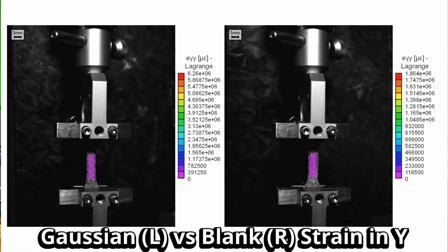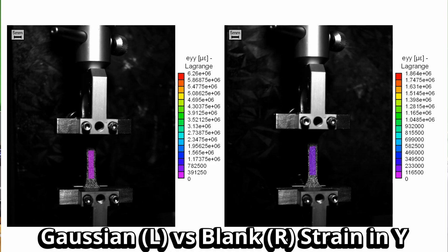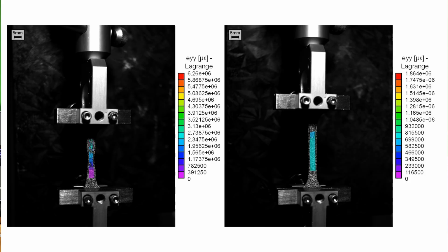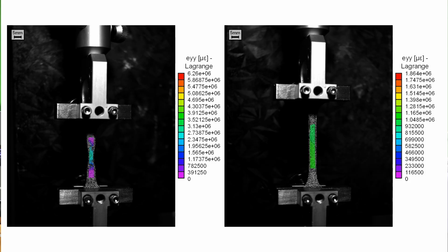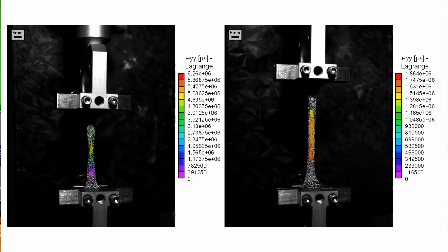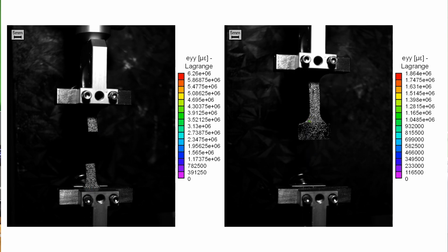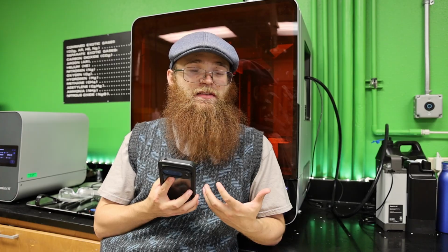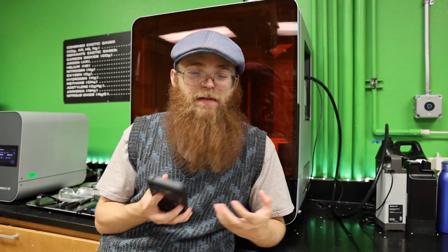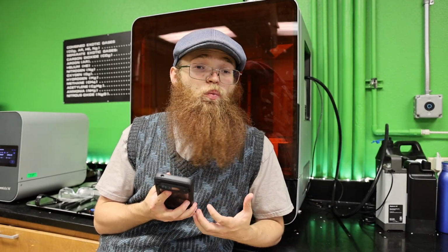Utilizing our working curve data, you can also try to utilize the different weird and wacky gradients that OpenVCAD allows for. And since you can line up the intensity of the lamp with how much cure depth our resin has, you can accurately predict what our resin will act like inside of different scenarios. So you can build more complex structures with even more complex material properties depending on whatever you need.